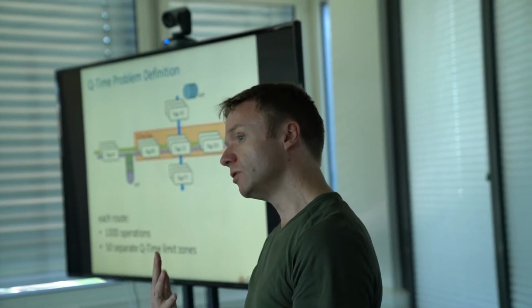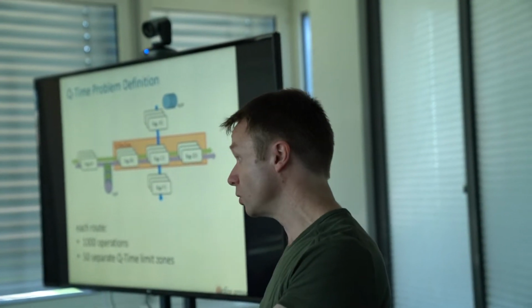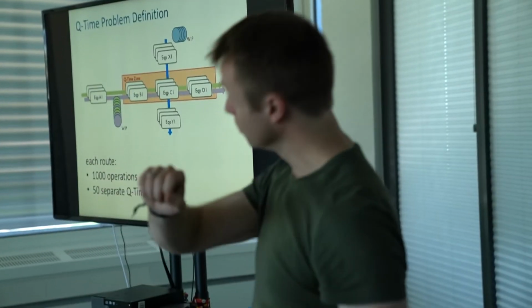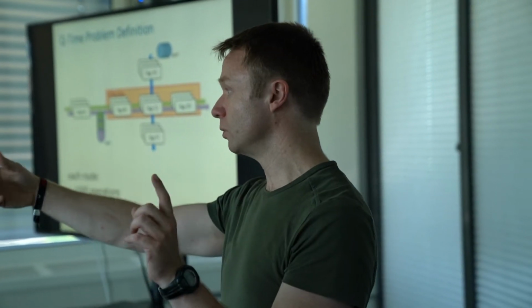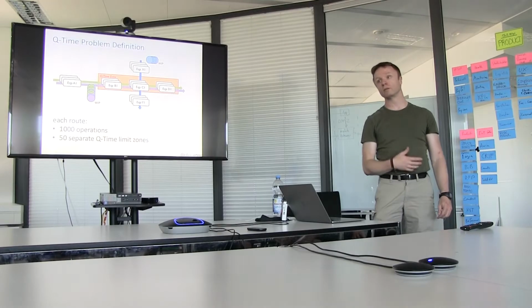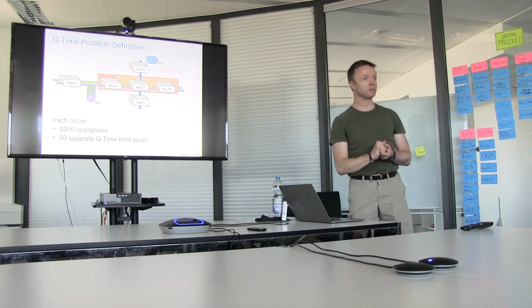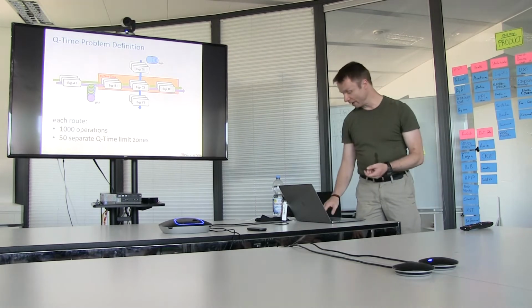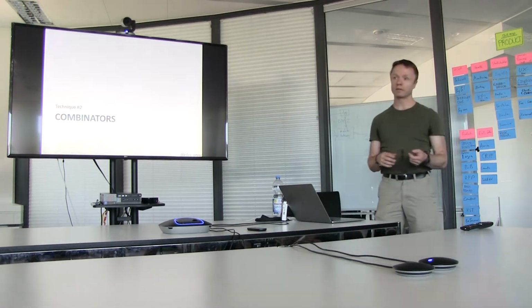And it means you need to be careful, because once you enter that queue time zone, you've committed yourself to finishing that part of your route within a certain amount of time. And if not, you have to throw away the wafer, and things get expensive, and management gets involved, and QA processes, and you all know what that feels like.